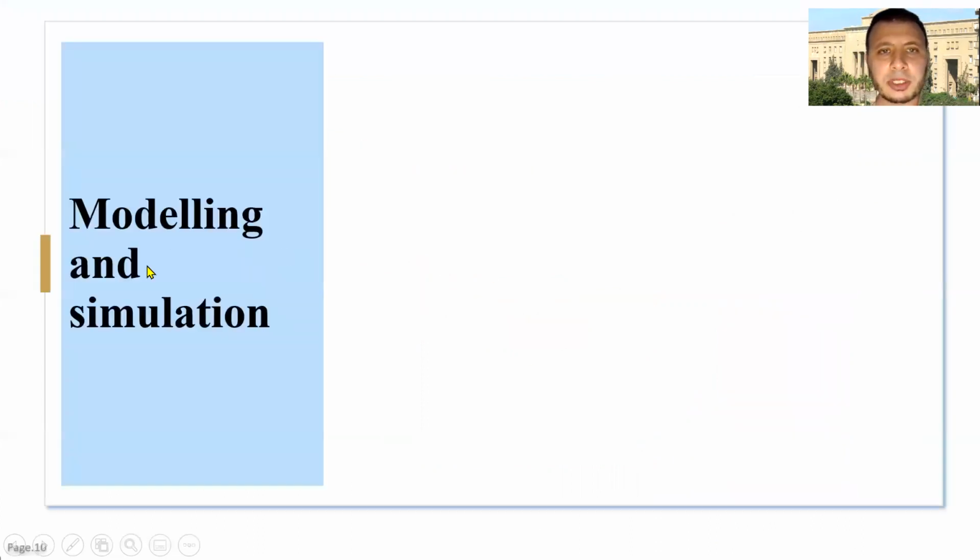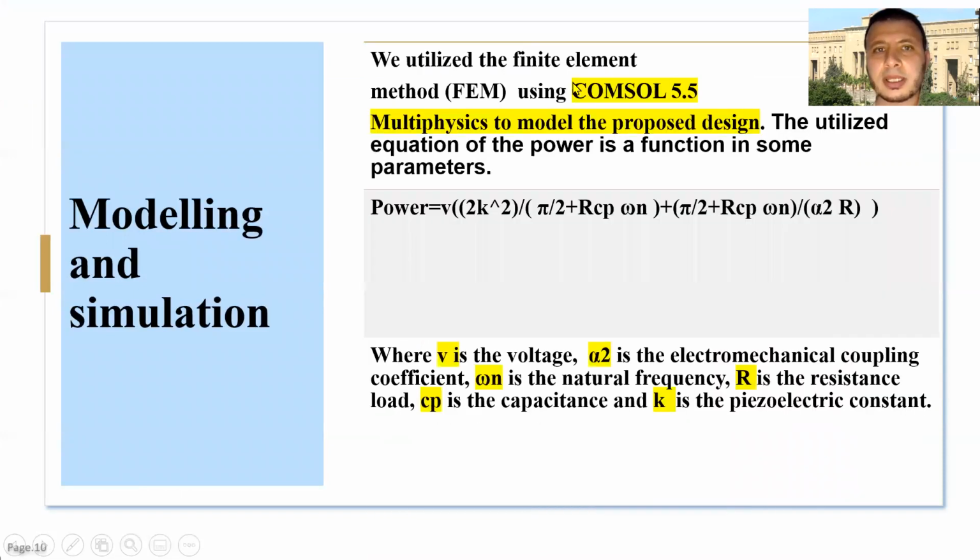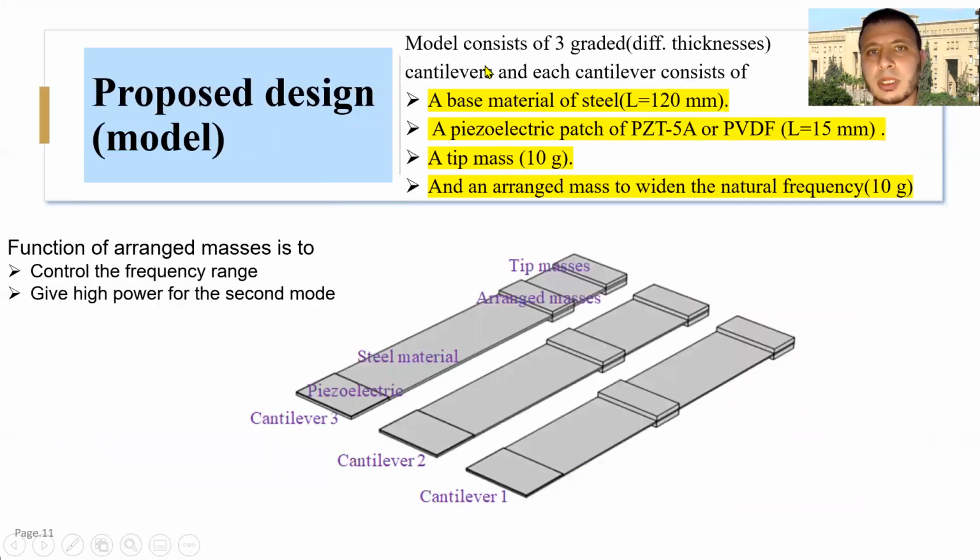Modeling and simulation. We utilize the finite element method using COMSOL Multiphysics to model the proposed design. The utilized equation of power is a function of some parameters: voltage, electromechanical coupling, the natural frequency, the resistance load, the capacitance, the piezoelectric constant. The proposed design model consists of 3 gradient different thickness cantilevers, and each cantilever consists of a base